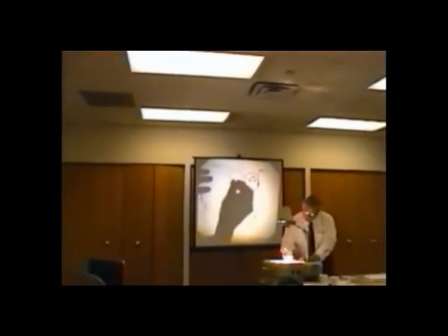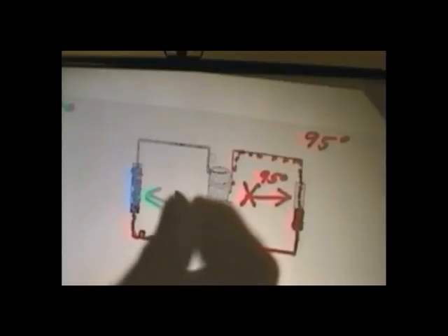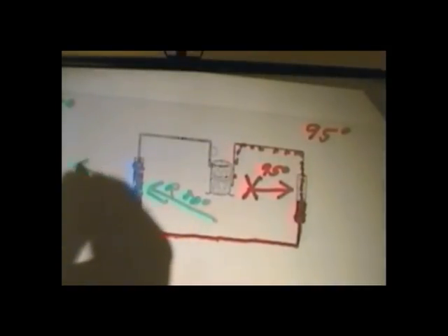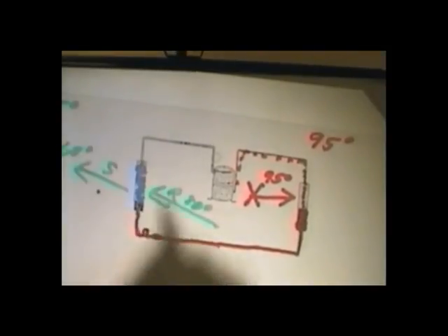So let's go back now. We have a normal system. And we actually, under these conditions, now have an evaporator that is completely full of liquid refrigerant, changing state, boiling, and it's absorbing BTUs. We could say, as an example, that we have, let's say, 80 degrees return. And let's just say everything is working fine, so the air goes through the coil, and we have a supply of 60 degrees. So we would have a 20-degree drop across the coil. And that would be terrific to have.